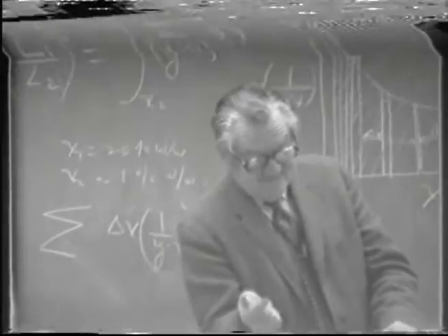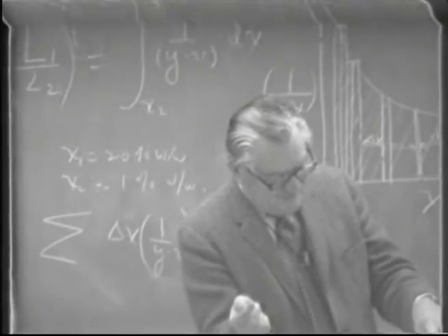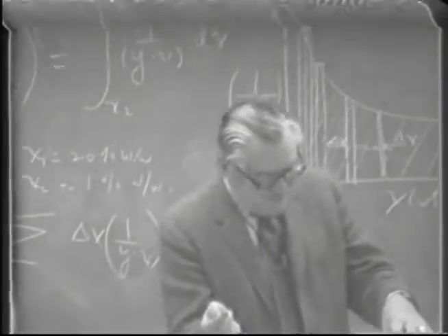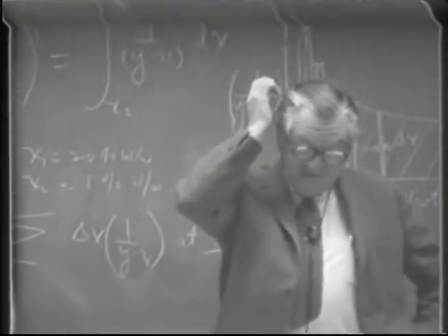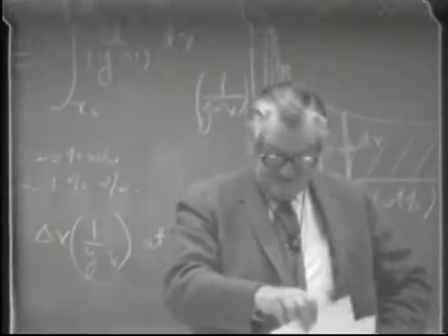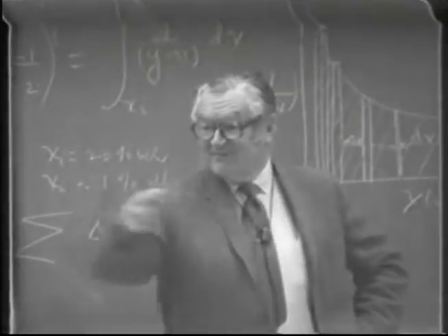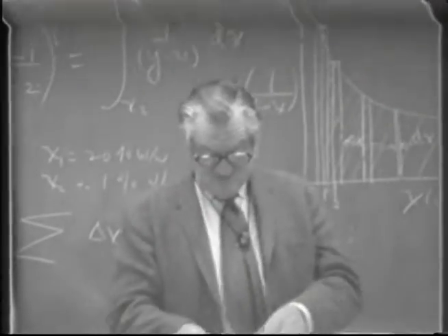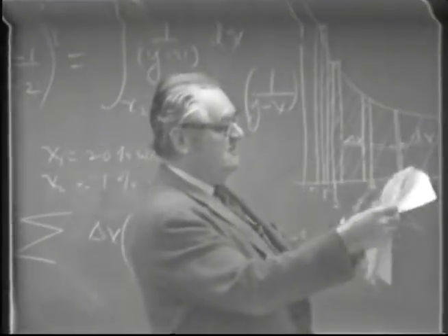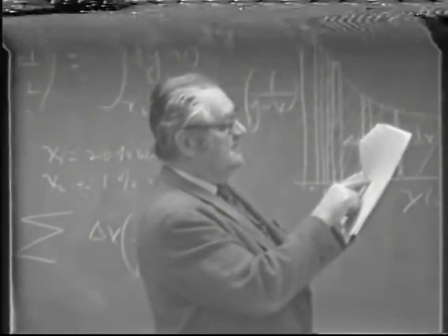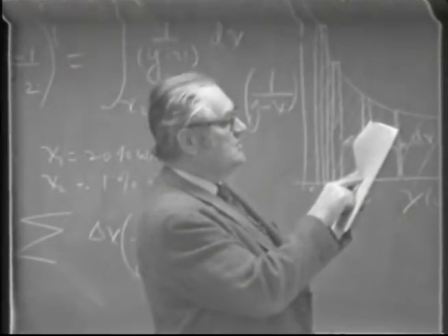And so the reason that the fusel oil suddenly appeared was maybe partly because, as these graphs indicate, we were adding so much water that it was dissolving the fusel oil and running it back in through the water layer. As you see in these charts here, if you add a very high amount of water, the percent of isoamyl alcohol in the wash water